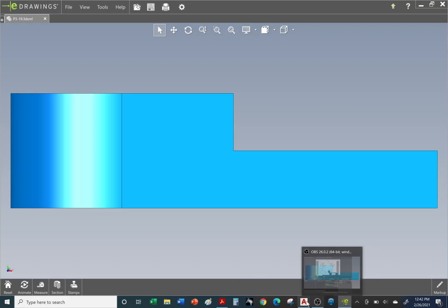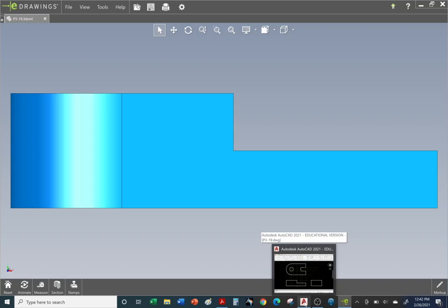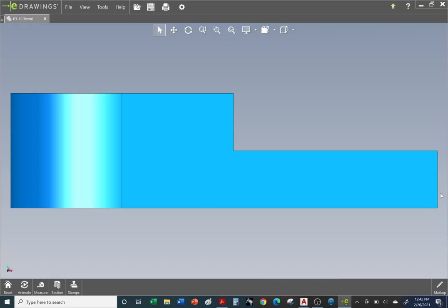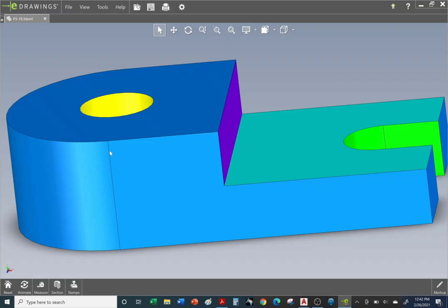All right, so let's go ahead and start the problem. We'll start with the front view. In the front view, we have all the object lines. Again, this is a tangent line here, and we do not draw tangent lines. Same thing with this one over here. Obviously from the front view, we cannot see the hole going through, nor this opening here. We cannot see it, but we need to represent it with hidden lines and center lines because we have a full circle and a semicircle.